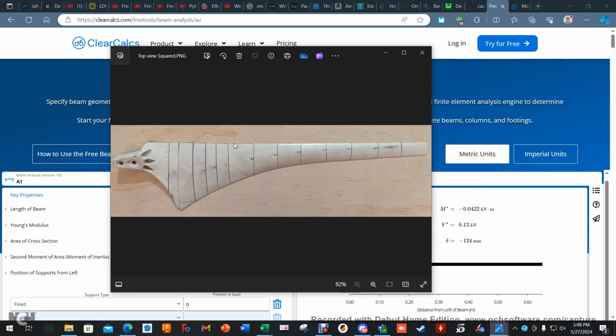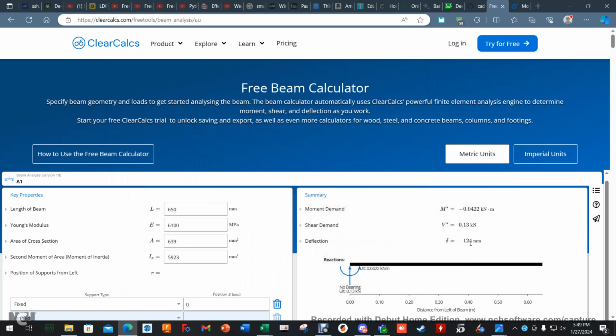But most of the material is right in here. So it's trying to find out, okay, if I were to draw a line straight across right here, I lose some, but I also gain some. So it's trying to find that perfect spot where you can have a rectangular beam. If I cut right here, I lose all of that beneath, but I also lose all of this empty space. So I'm hoping that this is enough to compensate for this. That's why I was able to find the average. I just went with a thicker material, found the average of that, and all the averages of the airfoils, which hopefully yielded a decent average, which it must have, because it was only 3 millimeters difference.